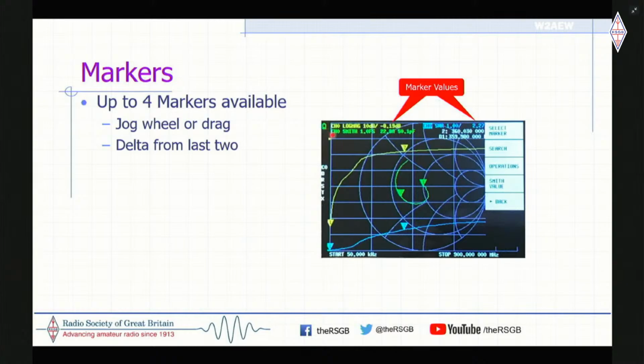So channel 0, for example, the green trace, that's on the Smith chart. That's on this curly Q chart here. That's this trace right here. Again, in this case, it's showing the complex impedance at marker number 2 is 22 ohms and 50 picofarads. Obviously, all these are on channel 0. The blue trace here is channel 0. That's on SWR. Okay, and that's the SWR trace down here.